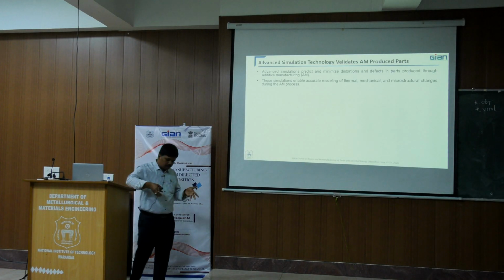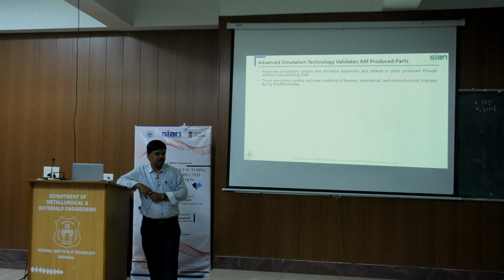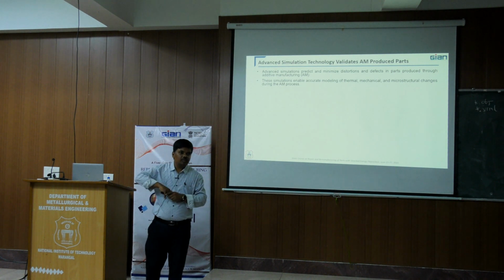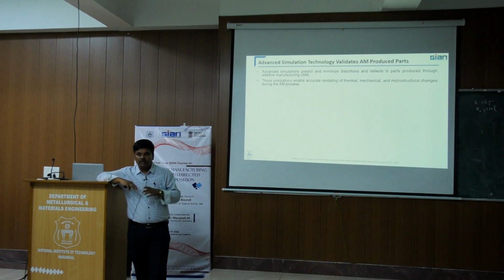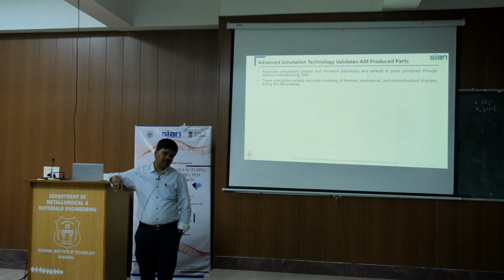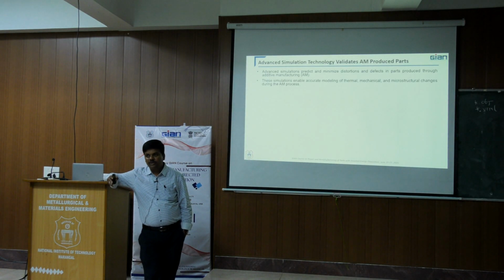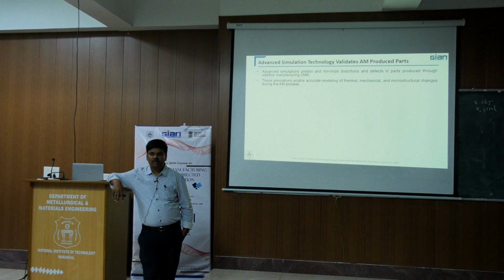If you do not understand the simulation aspects, it is a problem, because we have to do several iterations to find the optimum process conditions. We cannot run all the experiments with all kinds of materials. We need to know the optimal process conditions we can print with. Even if you print cubes with optimal conditions, that may not work for your real components. If I want to make a small bracket, the optimal process condition made for the cube is not going to work for the bracket.